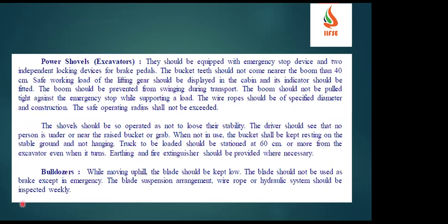Then power shovels, also called excavators, should be equipped with an emergency stop device and two independent locking devices for the brake pedals, and the bucket teeth should not come nearer to the boom than 40 centimeters. The safe working load of the lifting gear should be displayed in the cabin, and the indicator should be fitted. The boom should be prevented from swinging during transport.